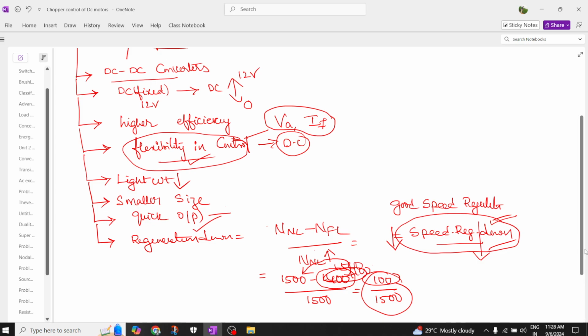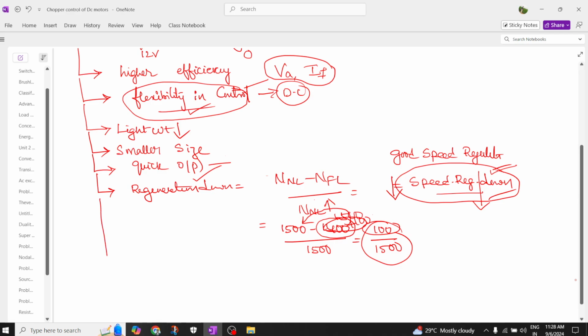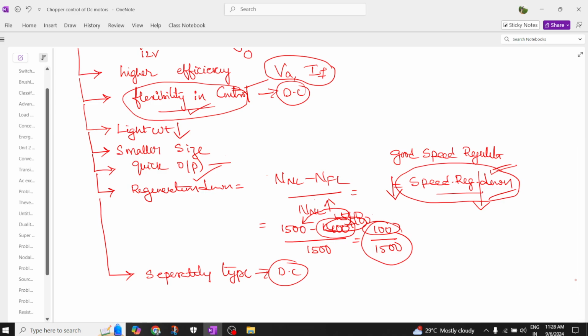In our electric vehicle drive, we are going to use a separately excited DC motor rather than a self-excited one. We use a separate type of excitation to control the speed in the case of DC motor traction. I think you know very clearly what the different speed control methods in a DC motor are. We have the armature voltage control method and the field current control method. Using armature voltage control, we can run it up to less than rated speed. Using field current, you can control the speed up to beyond rated speed.